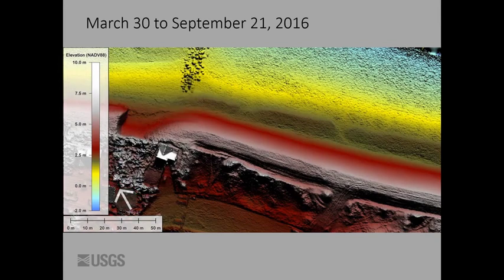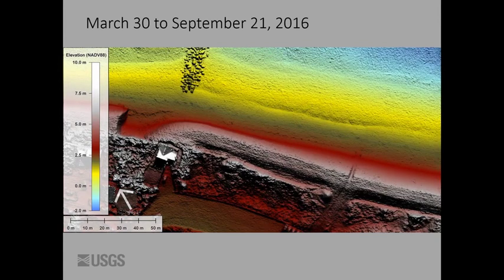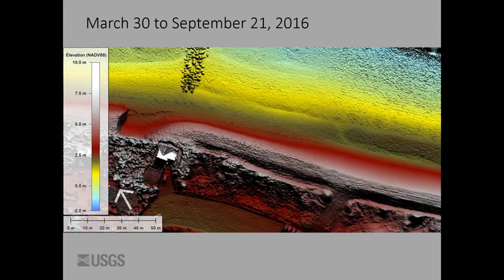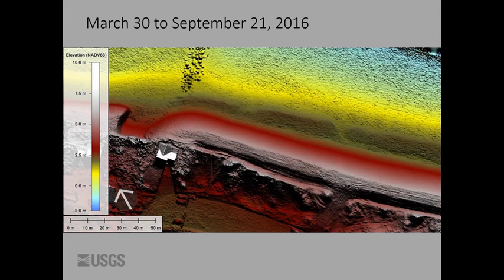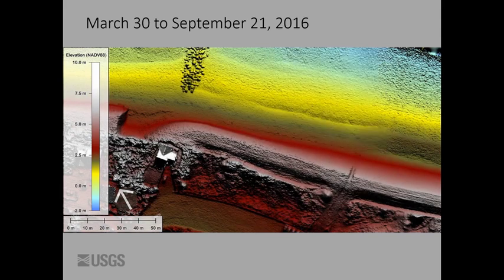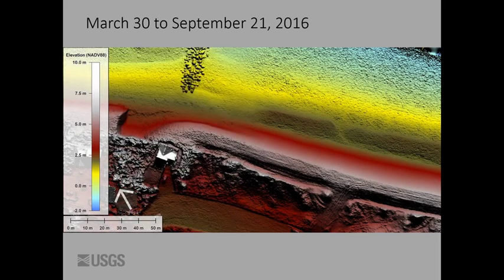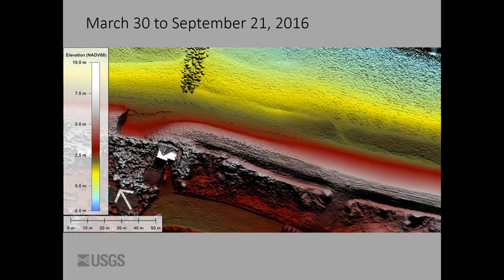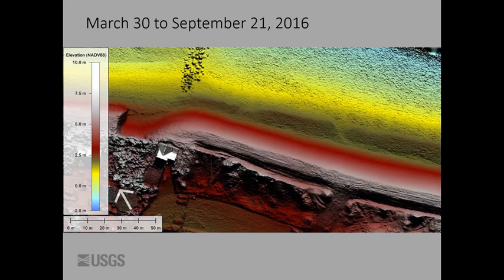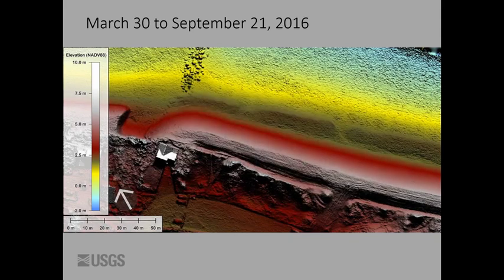So this is the same thing, but now looking at the digital elevation model. These are two of the models from the drone flights, and you can see stuff that's not supposed to change doesn't change, like the house hasn't moved. Cars moved. They had a little Jersey barrier here, and cars were here, and then they left. You can actually see the dune grass grow in this because they planted it not long after this first one was taken. It grew all summer long, and it's now fairly high.